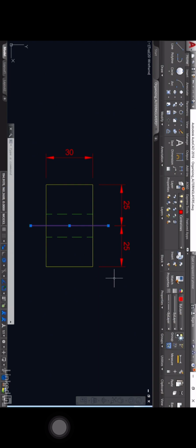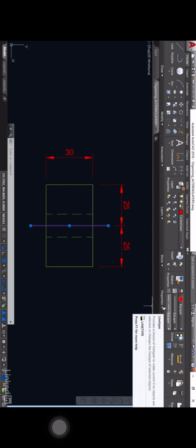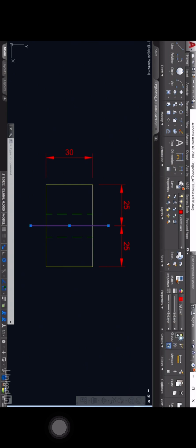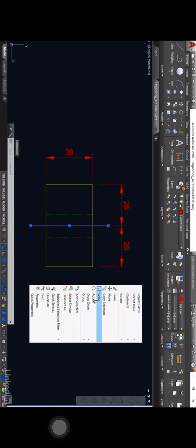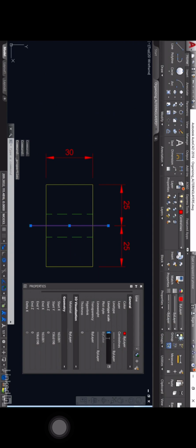But you'll notice it looks like one continuous line. Now, I said I was going to come back to that by layer setting. If I go and look at the properties panel now with my center line selected, can you see by layer it should be using a center line type? So if I just hit Escape there a second to deselect it and jump into my layer properties, you can see here that center lines are using a center line type. So why is it showing as a continuous line? Well, if I close the layer properties manager, you'll remember in the previous video, we looked at the line type scale. Now this affects things like dashed lines in your drawing. So if I select that one particular line and I right click and I go to Properties, and I change the line type scale to 0.2 like I did in the previous video, and press enter, you'll see that we now have a visual of the centerline line type there.